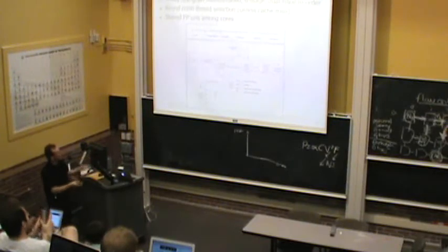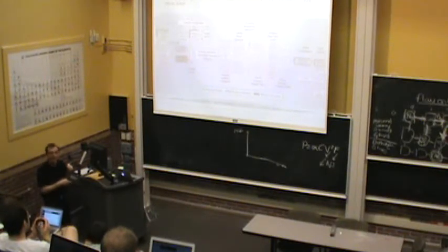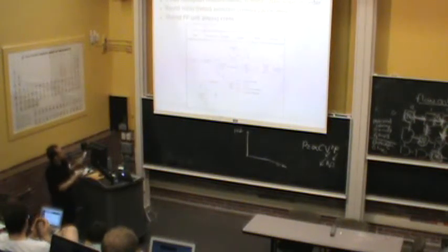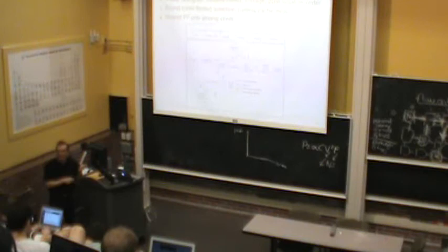But if you look at the pipeline, it's really simple, right, compared to this, if you will, with all the out-of-order execution. So this is the small core approach. And if you look at single thread performance, what do you have here? I think you fetch from the same thread every 4th cycle. So your throughput is very low, right? Just 1 instruction every 4 cycles.